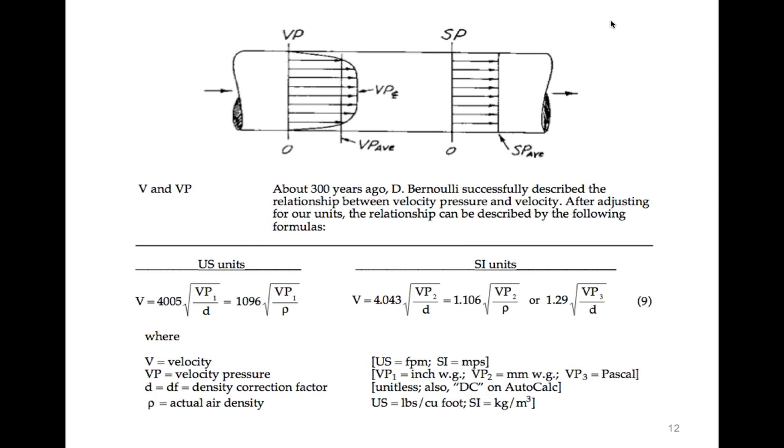So imagine if we put that tube there, it would go the opposite direction. Air would push down on the tube instead of suck up on the tube. We probably won't be here together next week. The following week, we're going to go down to the lab for half an hour. We're going to set up a fan and a duct, and we're going to do this so we actually see this work. Okay, so the static pressure on one side is negative, on the other side is positive.